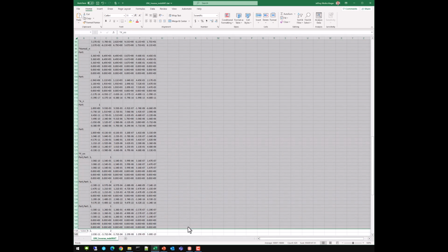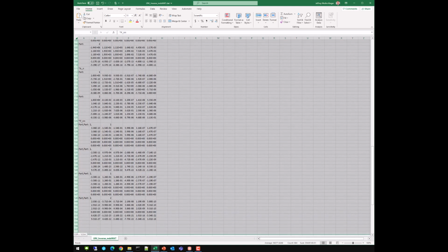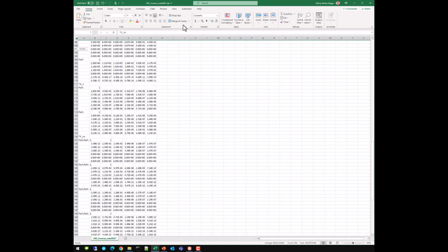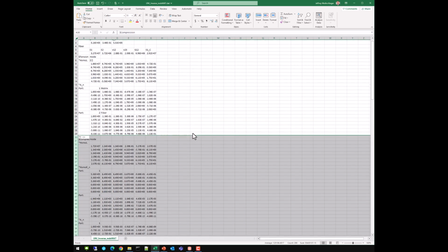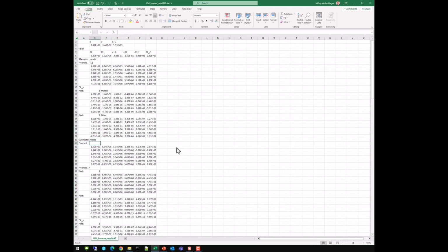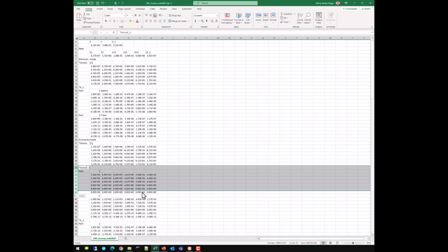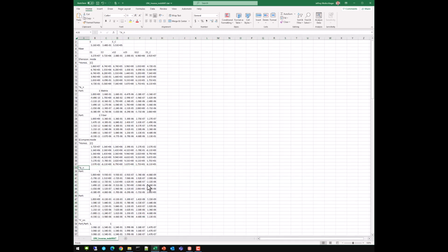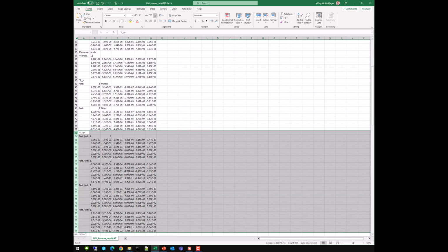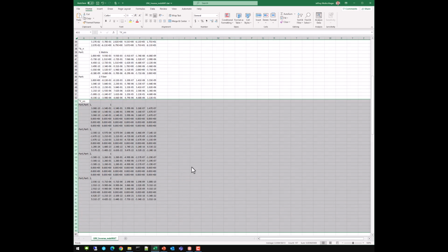We don't need these for any of our linear calculations, so we can just go ahead and get rid of all the P's to the compression mode line. This is my stiffness matrix in compression. I can get rid of the homogenized ENs, and I can keep the amplification matrices again for the matrix and for the fiber, but now in compression, and I can get rid of everything else to the bottom of the file. It's just not necessary.